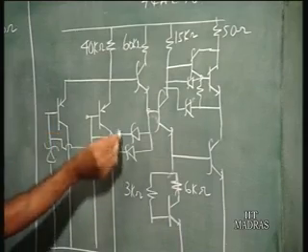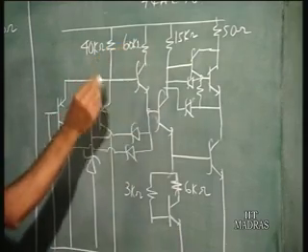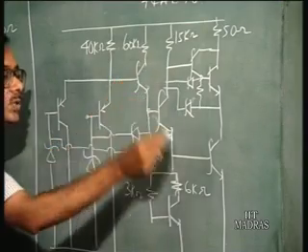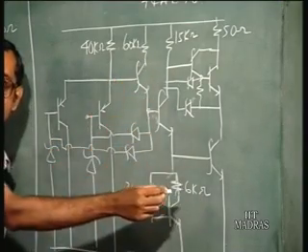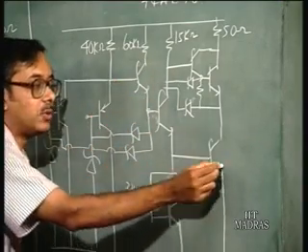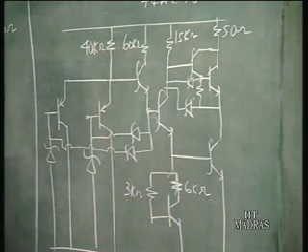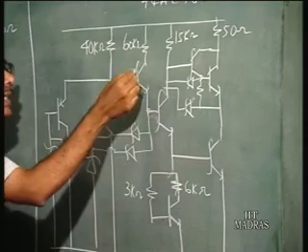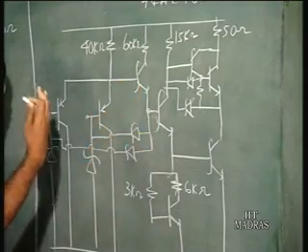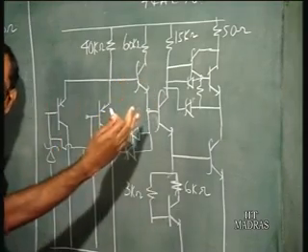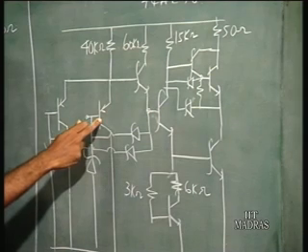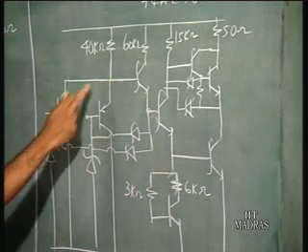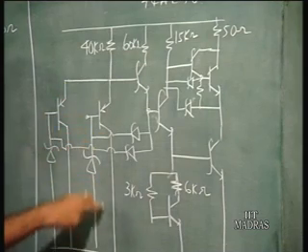So, to summarize, you have an additional transistor here, the purpose of which is to increase the internal current gain, so that the output pull down transistor can turn on faster. But to compensate for this additional VBE drop here, because the characteristics is going to shift, a PNP transistor in the emitter follower configuration, this is the emitter point, has been introduced.